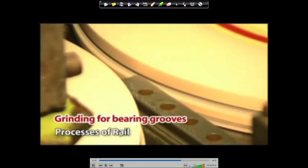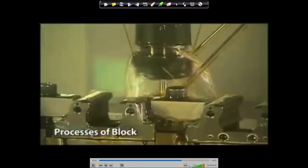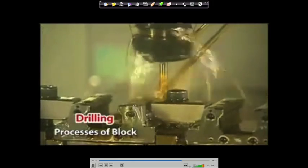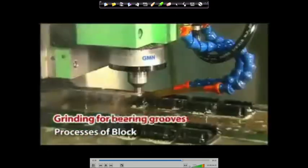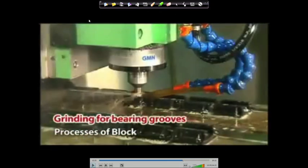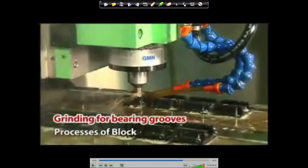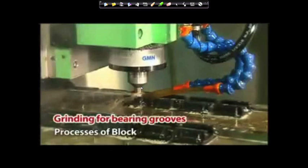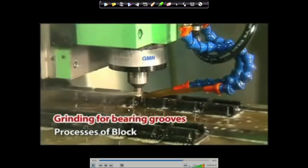Right. So, this is the processing of the rail, and the same thing we have to do for the block also, because we have to mount one block on the top. Again the drilling and all the operations are the same, and again you have to create the reference surface, because both are matching parts. Earlier what we discussed was for a single component, but if you have two components which come into contact with each other, then you have to create a reference surface for the other one also. After that operation you have to grind the bearing groove also, because you have to make sure there are no dimensional problems. Tolerances should be as tight as possible, so that you avoid any problem at a later stage.